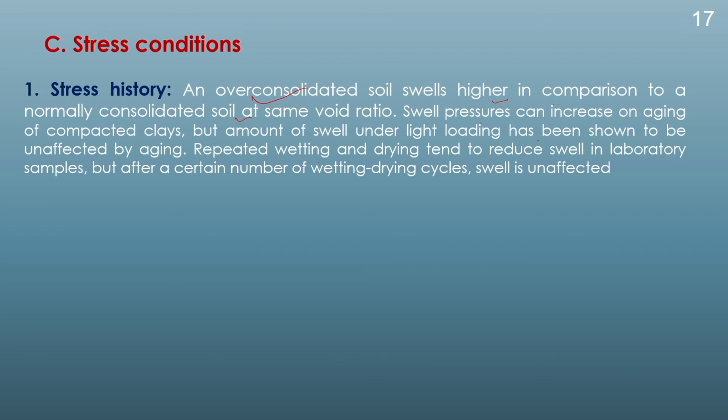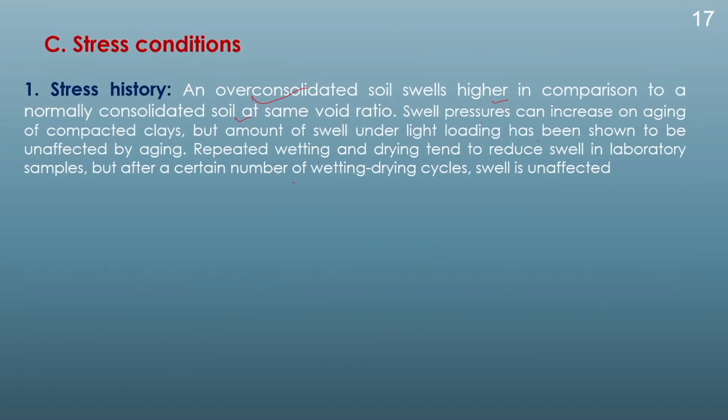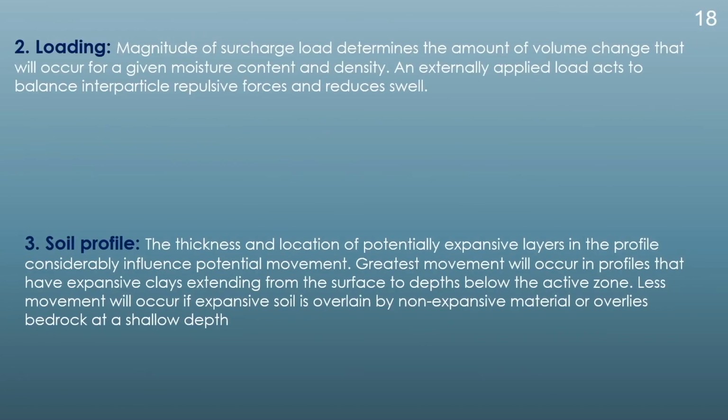And repeated wetting and drying tends to reduce the swell in the laboratory samples, but after a certain number of wetting and drying cycles, the swell is unaffected. The other factor under the stress condition is the loading. The magnitude of the surcharge load over a soil can control the swelling behavior.